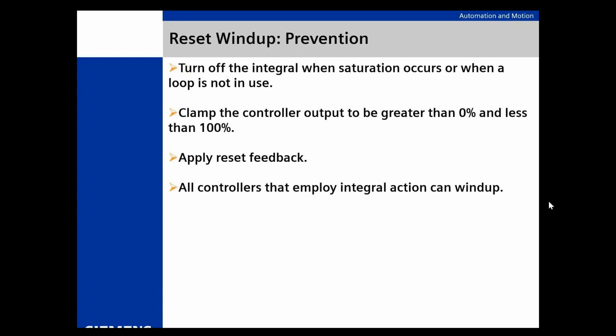What you'll see is if you leave the controller on and you have a valve out there, I can't tell you how many times I've seen that valve sit there, it's off. You know, the power's still on, but there's no flow, and they're working on the plant. That valve will start to go up and down and up and down. And a few hours later, it's going wide open, wide closed, because it's wound up. The controller's not getting feedback from the flow meter or whatever, so it doesn't know what to do with that. So it's looking around trying to get a signal.